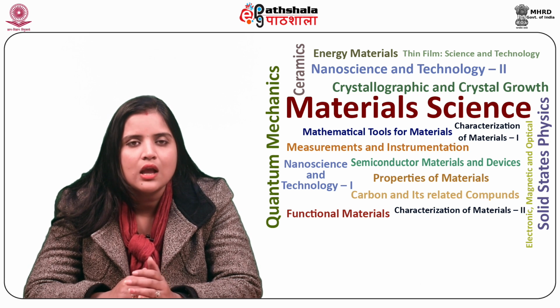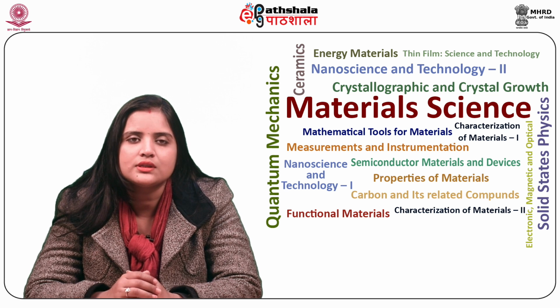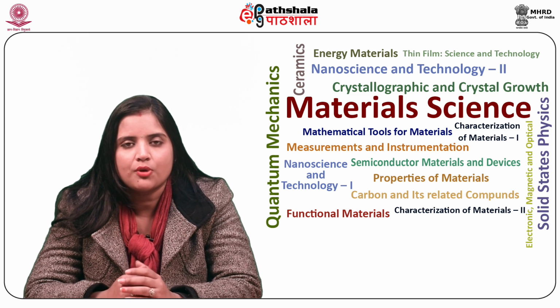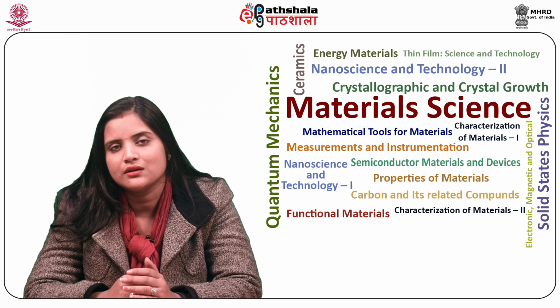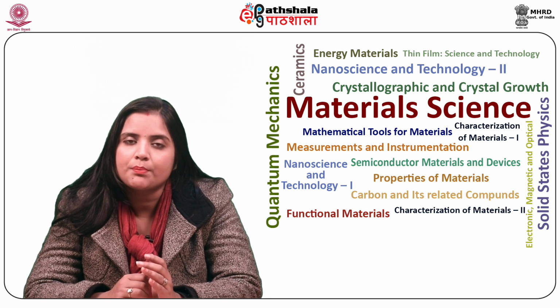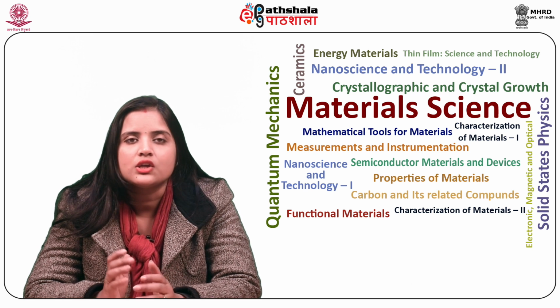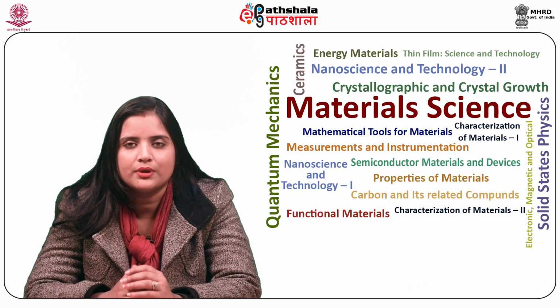For instance, nitrogen is employed to enhance the wear resistance in metals. Substrate cleaning prior to the deposition process is highly critical in this technique, as it works on the species which are present on the surface of the substrate. Therefore, it is highly prone to contamination-led problems.